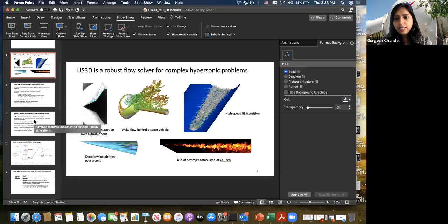So then I did a grid convergence study, a numerical convergence study, and I found that if you increase the number of those sub-iterations from 4 to 30 or 100, you increase the accuracy in wave speeds. Finally, I used a value of 40 sub-iterations in my calculations. I think it would have been helpful if I presented my PhD work, but for this presentation, I just wanted it to be an overview.